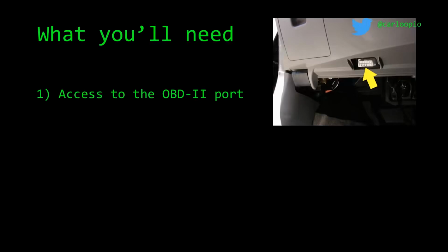The interesting thing is, since 2008, OBD2 was mandated to be on CAN, the CAN protocol, and I'll talk about that in a little bit. This is very important because the rest of the car is also on the same CAN network.